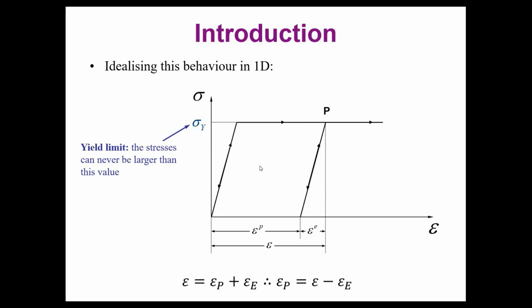For example, on the screen now you can see what we typically call an elastoplastic model, and in this particular case this is an elastic model because you have the straight line in here with a certain slope that is the Young modulus, and the plastic regime is a perfectly plastic regime because this straight line, the second line of the bilinear model, is a horizontal line.